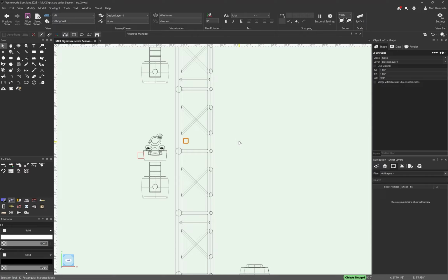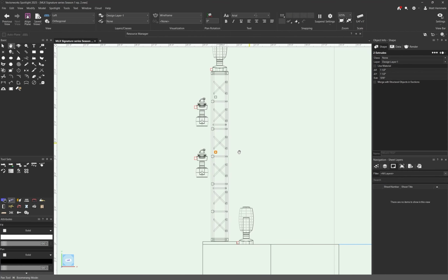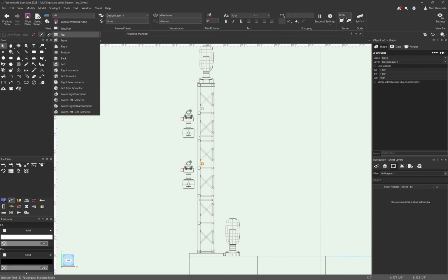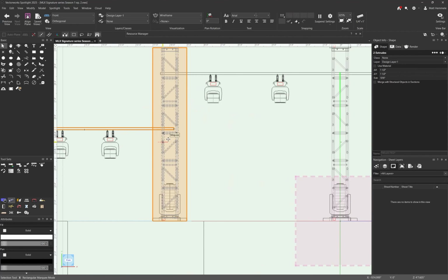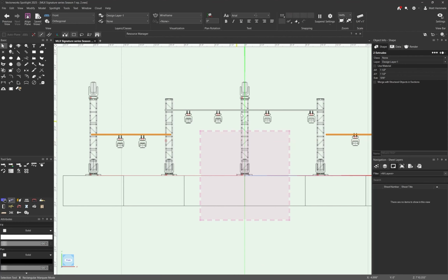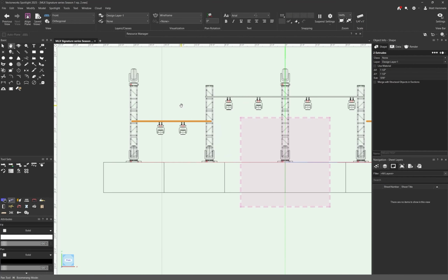So you can see objects nudged down there. That's just shift up and down, left, right, whatever. That's just nudging it a little bit; there's not a set distance. Whereas Control Shift up, down is that custom distance that we have set at 1 foot. So we're going to look at the front here and we're just judging height a little bit. And for now, I think we're going to call that good.